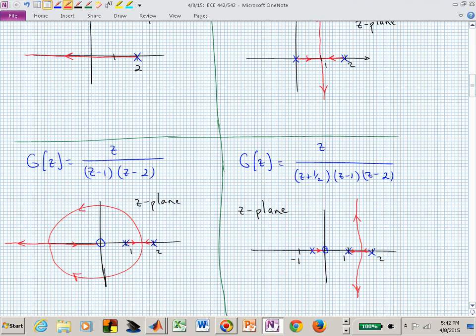In the upper left, we do have an infinite line segment that's a part of the root locus, but we also have an infinite segment that's not on the root locus. We have 2 line segments. And how many branches, root locus branches, do we have in the upper left? How many poles do we have? 1. So we have 1 root locus branch.